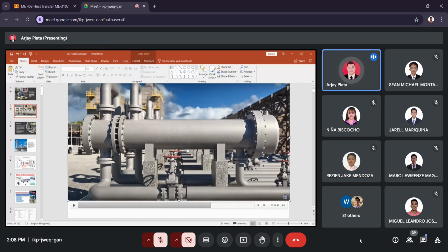So we have here a tube sheet. This one is the tube sheet. So the end of the shell, and then connected by a flange to the channel. So this is the channel part. These two are the channel part. So channel 1, channel 2. So channel 1 is a bonnet type wherein it is welded to the shell flange, while the left channel, sorry, is a flange type, is removable.